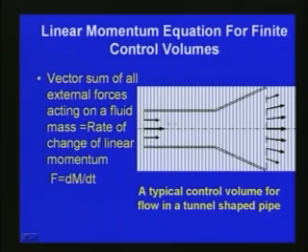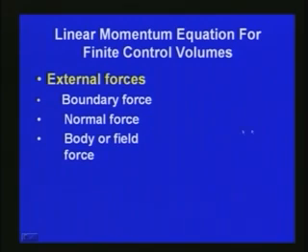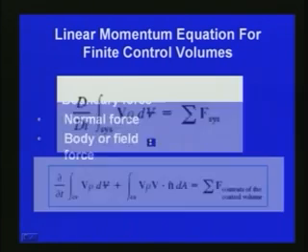With respect to the flow coming inside and flow going outside, there will be normal forces. So we have to consider these normal forces, and then of course the internal forces or the body or field forces. So the forces we have to consider include the boundary forces, the normal forces, and the body or field forces. These are the forces for a control volume when we consider the linear momentum equation.